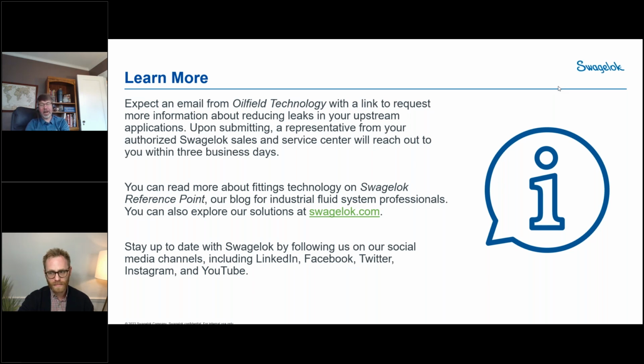It'll either evaporate away in some cases, or it'll wash away. And what's left when that washes away is now a continuous pore structure. So if you're relying on that grease to clog up that continuous pore structure, it will, but only temporarily, and it might take a year to wash away, or 2 years or 3 years or a month, but eventually it will be gone and there will be leakage.